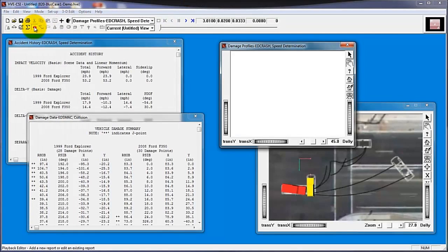The playback editor is used to create output reports. Unlike the other editors, the playback editor may display multiple viewers, called report windows, each containing different output results for a particular event. These results may be numeric and graphic reports, trajectory simulations, and variable output tables. The playback editor also provides the ability to create a simulation movie.